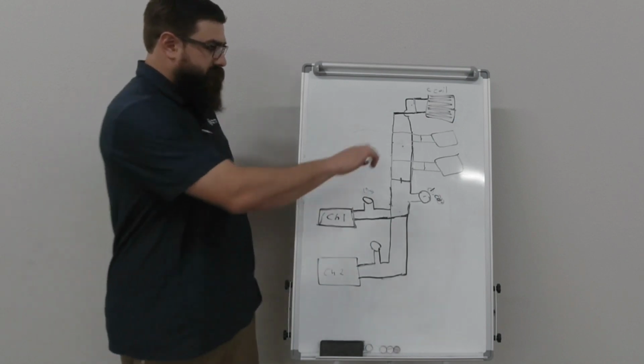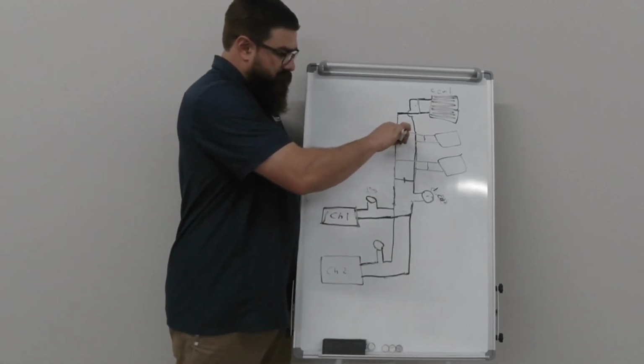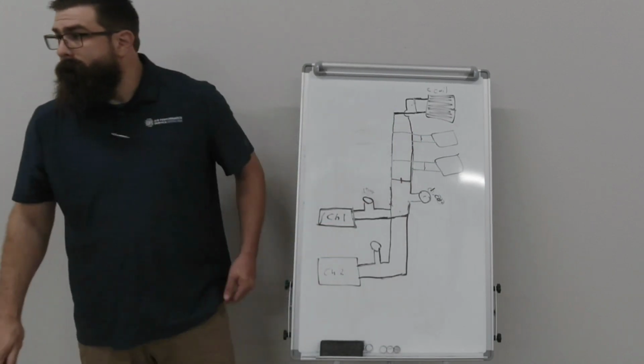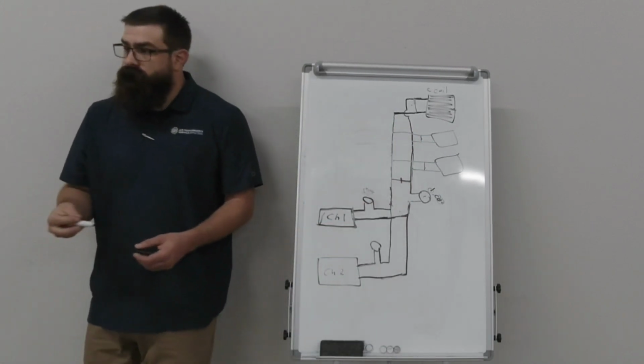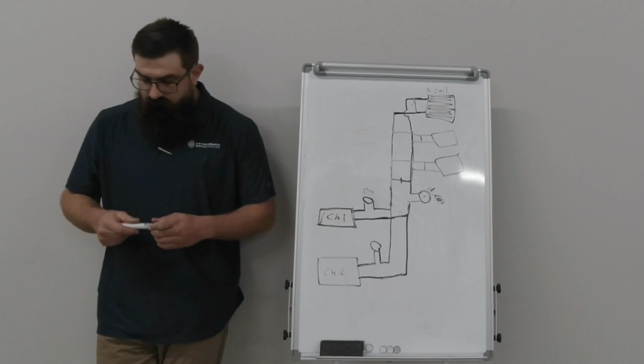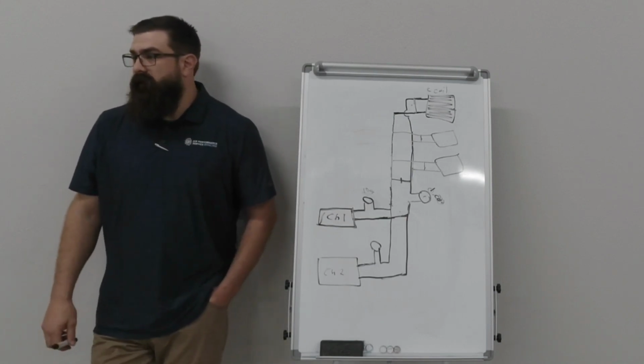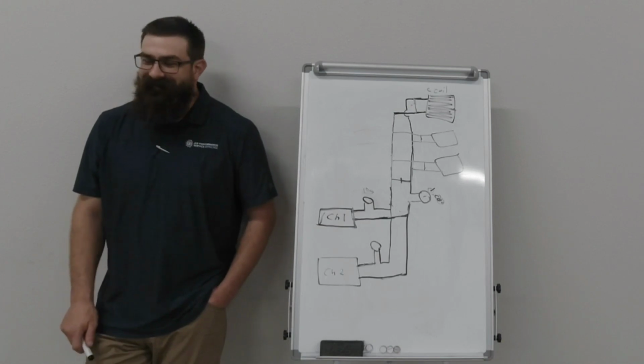Typically, you see those chill water bypass valves on just the variable primary. On your primary, secondary. Right. And most of the time they're at the end of the loop. Yeah. Or they're in the plant right off the chillers.